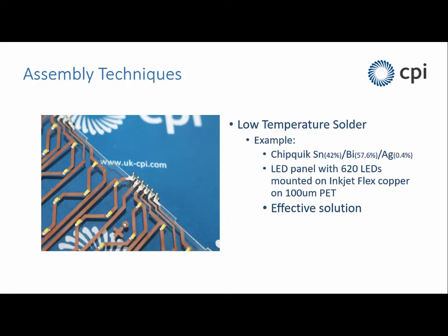And you also notice that we've got some through-hole components here. We've got an edge connector poking its pins through, which is also soldered onto this particular assembly. And that produced a very nice way of doing a feed out onto a conventional drive circuit. The drive circuit for this is large inductors and quite high power components, so we wouldn't have thought of doing that on the flex. So you've got to think about the sort of partitioning of your system, if you like. What fits well onto the flex technologies, what fits better onto the rigid conventional components, PCBs rather. So you need to think that through. But this was a very successful assembly.